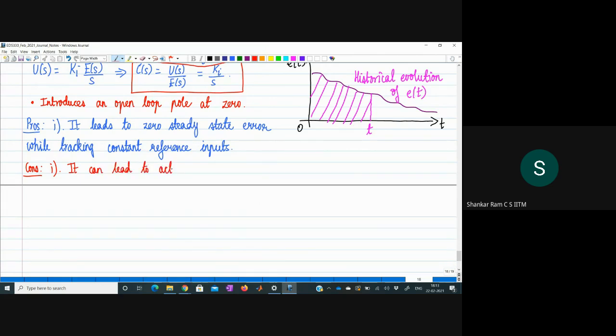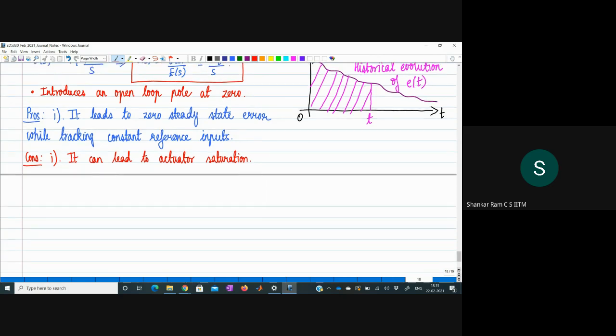actuator saturation. So what is called actuator saturation? Suppose we have a force actuator whose capability is 100 newtons of force, just as an example, and we demand, let's say, 105 newtons from it. The integral controller calculates and demands 105 newtons. There is no way that actuator can satisfy that, so consequently we are going to have what is called actuator saturation. So the expectation from the integral controller may exceed the capability.